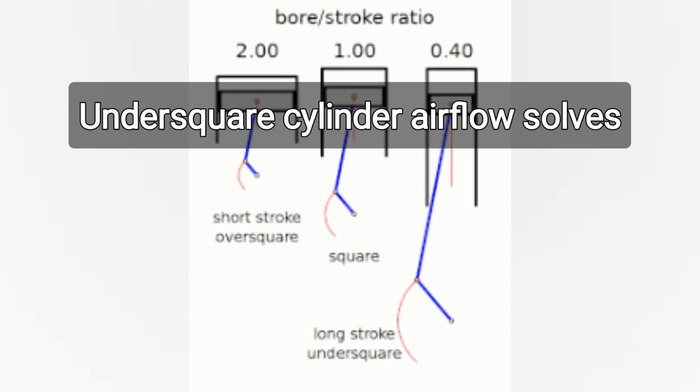Because the gear is bigger or smaller, that means changes in velocity and time duration for that given thing going on. So because the rotation of the crankshaft, in terms of time for gearing, has increased or decreased at various stages, you've gained a variable valve duration depending on where it is in its placement at top dead or bottom dead center.